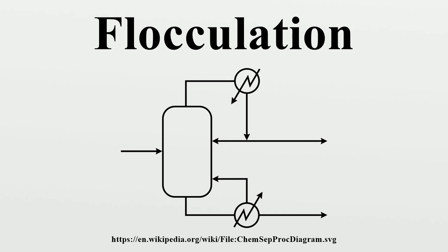Brewing. In the brewing industry, flocculation has a different meaning. It is a very important process in fermentation during the production of beer where cells form macroscopic flocs. These flocs cause the yeast to sediment at the end of the fermentation. Subsequently, the yeast can be collected from the bottom or the top of the fermenter in order to be used for the next fermentation. It is not to be confused with sedimentation in colloidal dispersions, as the mechanisms are different even though they appear to be pretty similar.